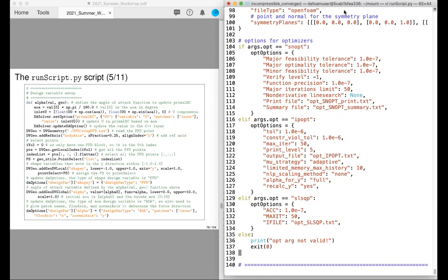Okay, that's a very common scenario. The short answer is that if your optimality drops below your tolerance, the optimization will automatically stop. As you probably saw in this tutorial, it will stop automatically at 17 iterations, although we allow you to run for a maximum of 50. But in a lot of cases, your optimality will not drop to 1e-6, so we just manually stop it. You can monitor your job, and if your objective function is not really changing but your optimality is still not 1e-6, you can just manually kill it.